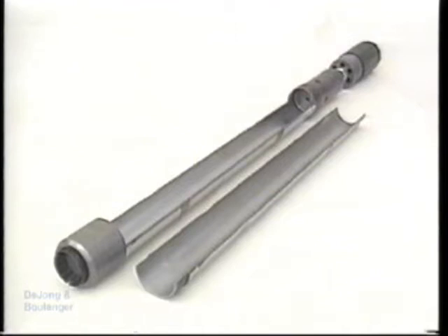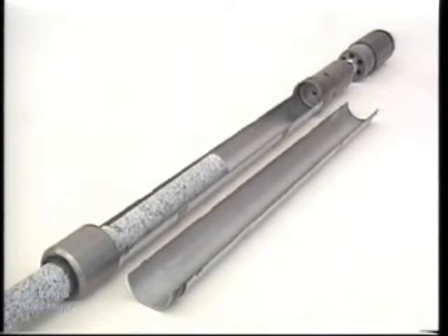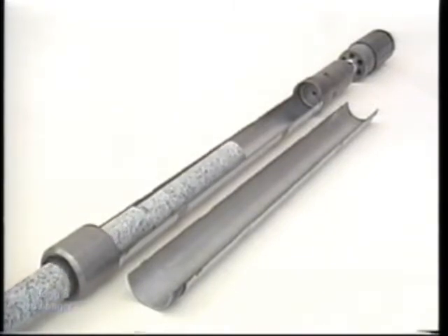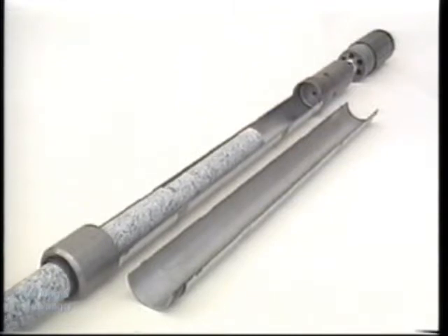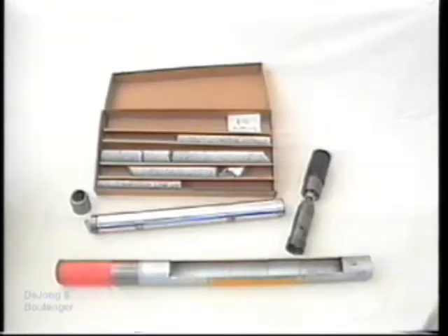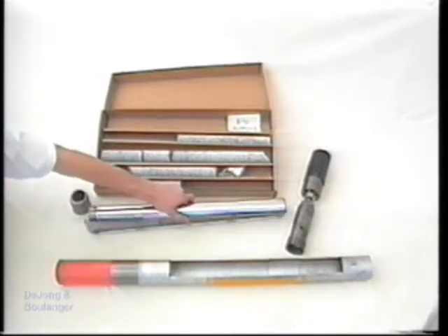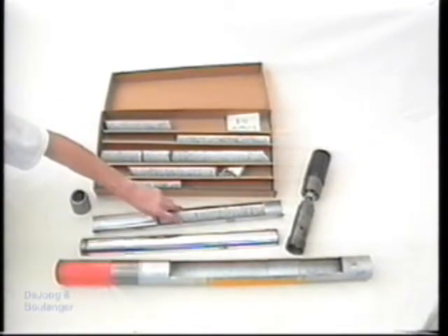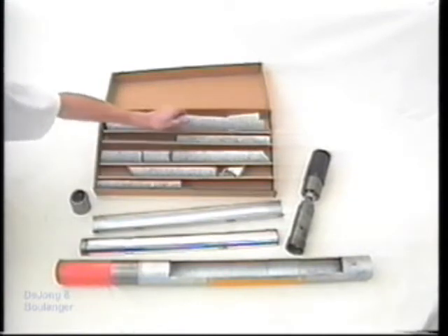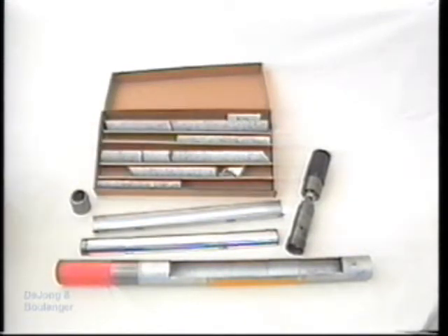As the core barrel is rotated and lowered, the core bit cuts an annular section out of the soil or rock. This section, called the core, moves up into the inner barrel where it is protected from potential erosion by the circulating fluid. Once the inside of the core barrel is full, drilling is stopped and the core barrel is removed from the hole. By disassembling the core barrel, a continuous sample of the soil or rock is recovered. The sample is measured, identified, and stored in core boxes. After reassembly, the core barrel is lowered to the bottom of the hole and drilling and sampling are continued.